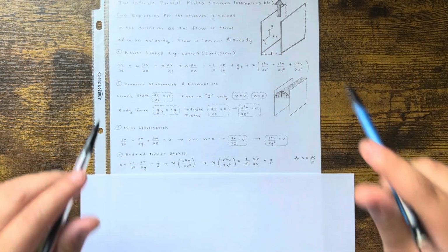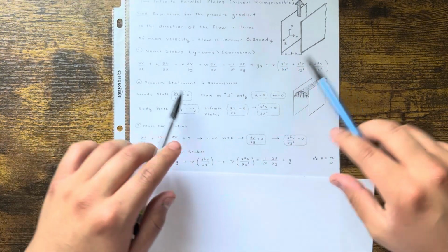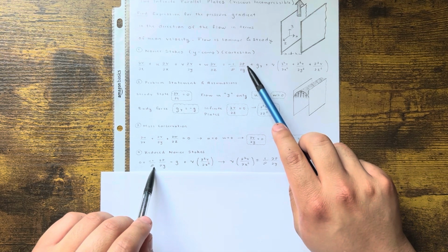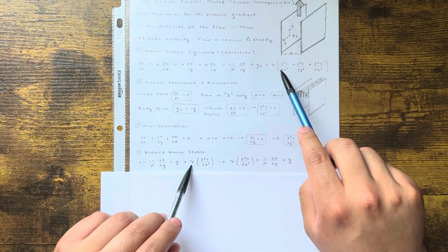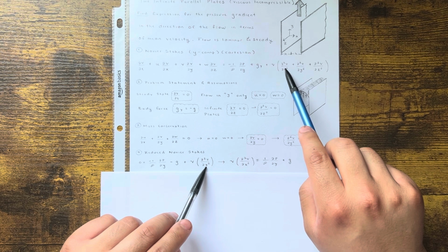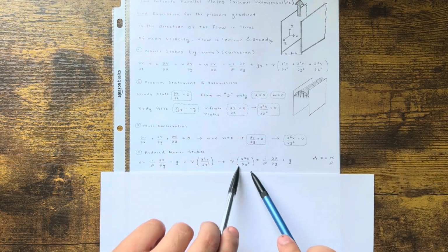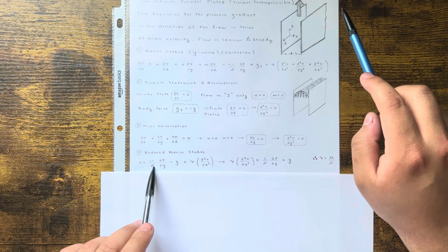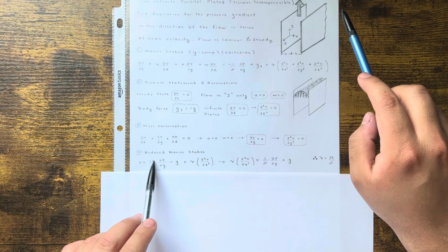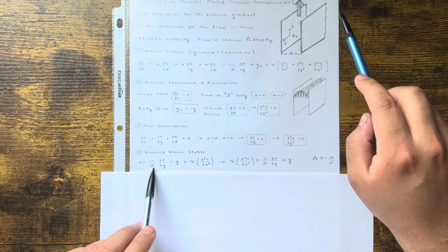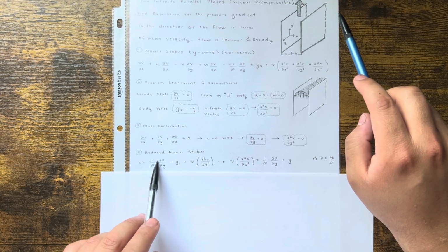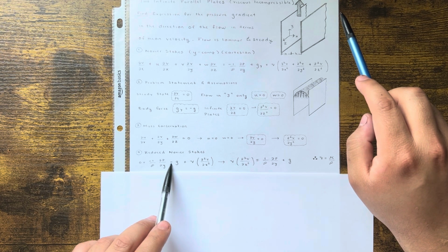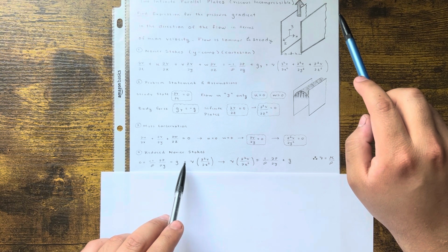So now that we reduced the Navier Stokes equation, we got all the terms that cancel out. Now we can just rewrite it. In this case, it's that term that I said, minus g plus nu delta squared v over delta x squared. Now I just rearrange it. I know nu is equal to mu over density. So what I did was I multiplied density to everything. So if I multiply density to everything, this goes away. It's just negative delta p over delta y. This becomes negative rho gy.